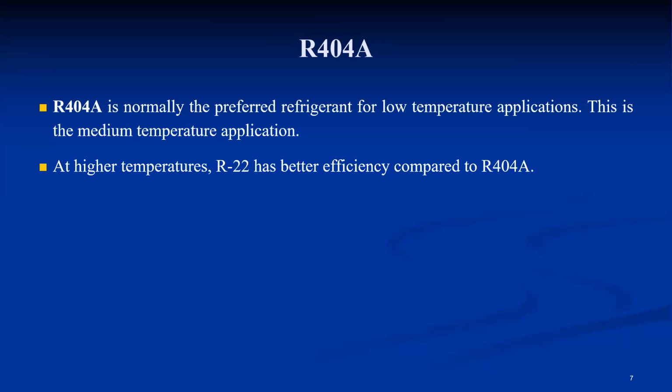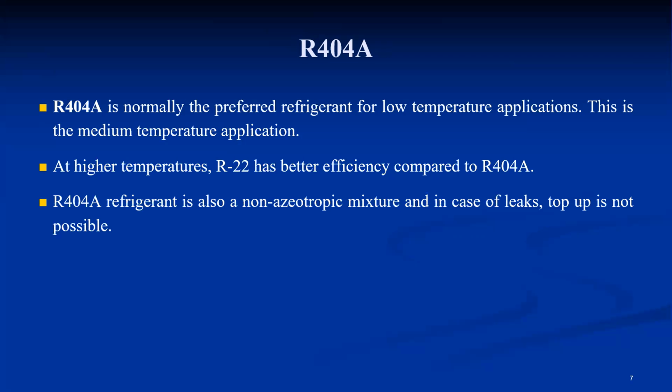Comparatively, it gives a better theoretical COP because of low compressor pressure. And R404A refrigerant is also a non-azeotropic mixture. In case of leaks, top-up is not possible. That is a problem with a non-azeotropic mixture. If there is a leak, the composition is disturbed, and in case of top-up also, the correct composition is very difficult to recharge. So the entire characteristic of the refrigerant may change.